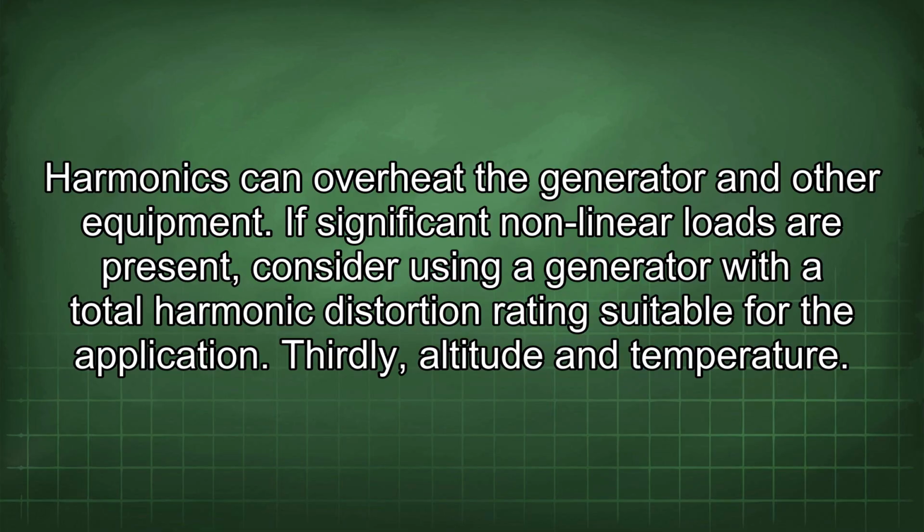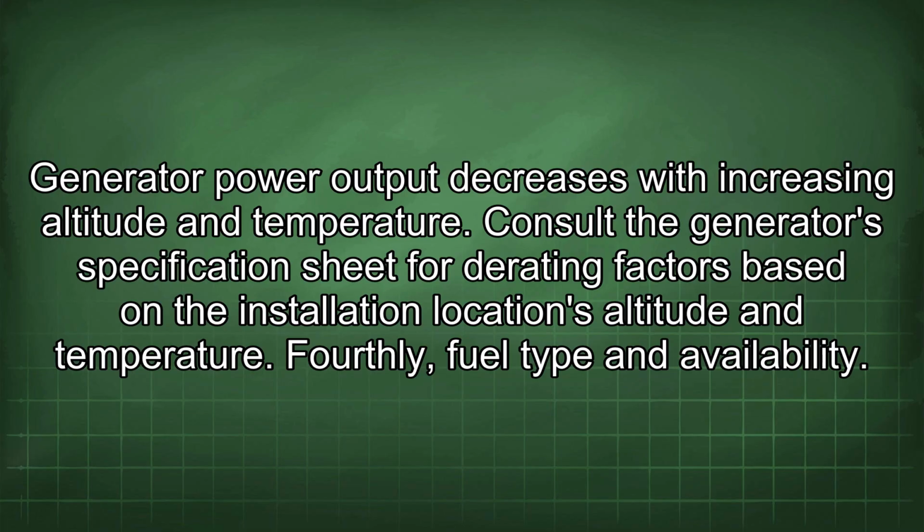Thirdly, altitude and temperature. Generator power output decreases with increasing altitude and temperature. Consult the generator specification sheet for derating factors based on the installation location's altitude and temperature.